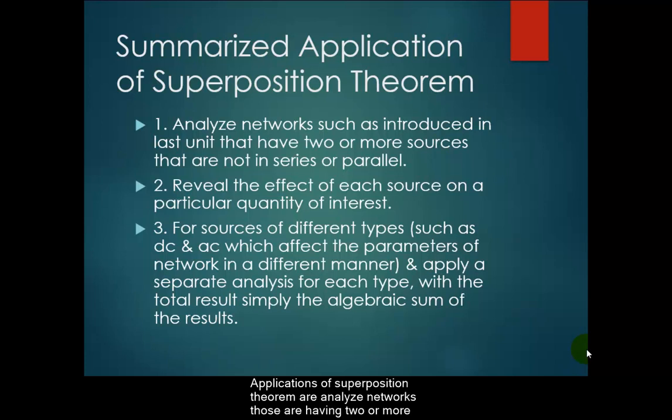Applications of the superposition theorem are to analyze networks having two or more sources that are not in series or parallel. Because if sources are in series or in parallel, no different analysis is required. Sources can be AC or DC.